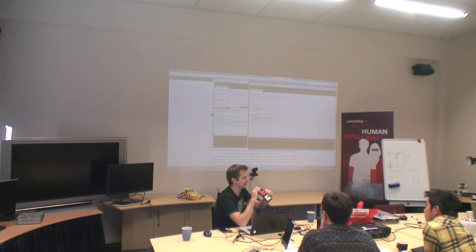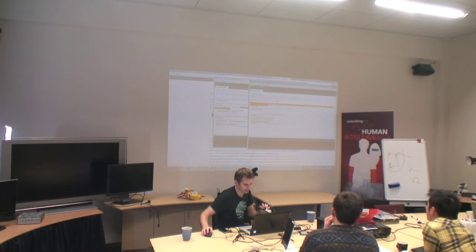The analog ones down the bottom are actually only for analog reading. You can use the digital ones for reading or writing digital and writing analog. These ones are just for reading analog, just to confuse matters a little bit. But yeah, so hopefully if I upload that now.